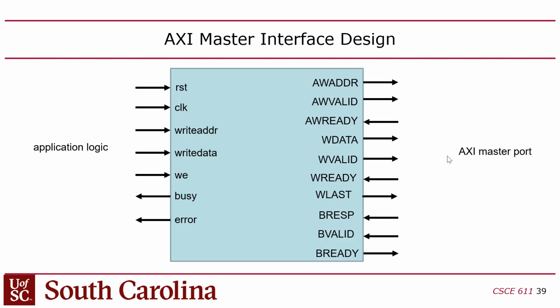Okay, so let's say now I want to create an interface for this. If any of you become hardware designers, you're probably going to have to do this, because by creating an AXI interface for your hardware design, you can drop your design into any system on chip that has an AXI bus, which is basically all of embedded systems. Make sense?